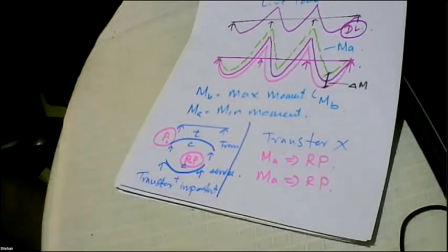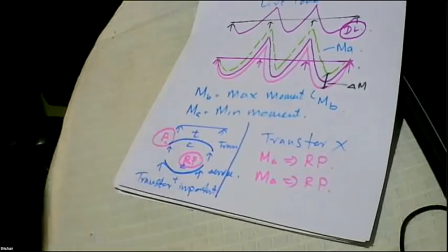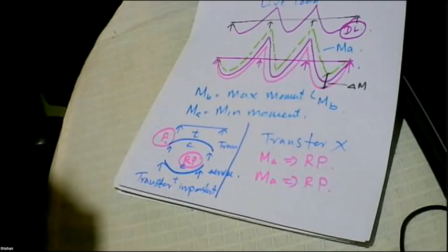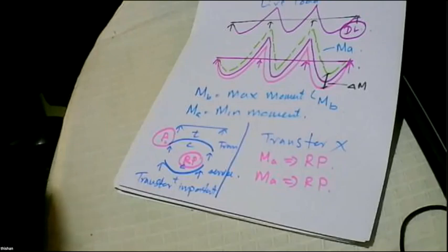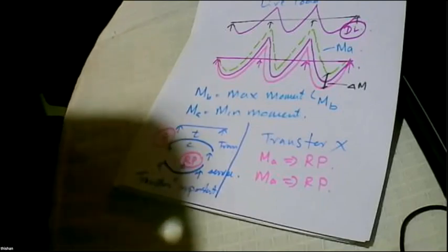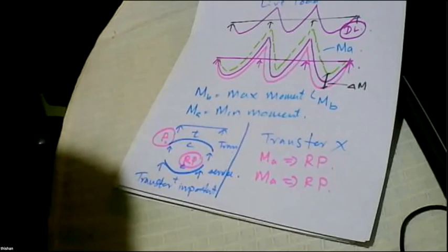There are two reasons. One is already the beam starts with some pre-stress, like bending upwards. Then you keep on loading until it fails. And when you are doing that, you find you are actually loading a member which is having very favorable conditions. So because of that reason, we always say pre-stressed concrete beams generally do not fail in ultimate limit state, and because of that, if you want, you can actually forget about ultimate limit state and do all the designs considering the service conditions.